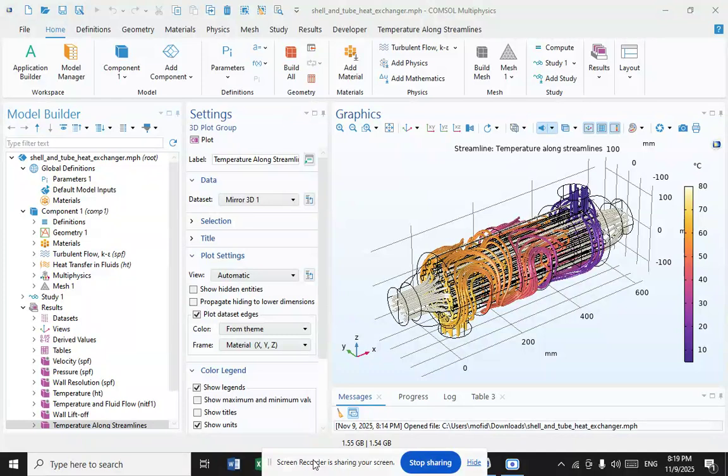The classic example of a heat exchanger is found in an internal combustion engine in which a circulating fluid known as engine coolant flows through radiator coils and air flows past the coils, which cools the coolant and heats the incoming air. Another example is the heatsink, which is a passive heat exchanger that transfers the heat generated by an electronic or a mechanical device to a fluid medium, often air or a liquid coolant.